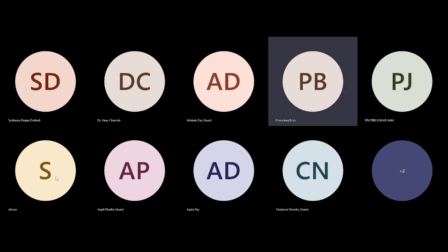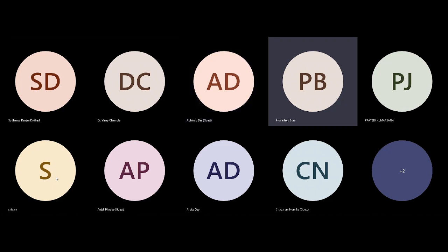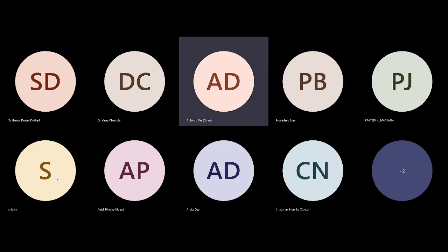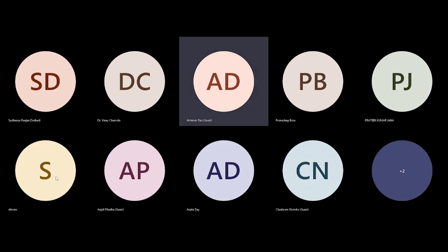Because you can see in the netlist tab, you are getting nets and leaf cells. The implementation doesn't know which is block RAM and so on. It will see all the design as leaf cells. So it is a LUT-based leaf cell that has been utilized, or a slice M-based LUT, like that. So the MUX is also a leaf cell, right? Yes, any component, any resource inside the FPGA after implementation will be treated as a leaf cell. Understood, thank you.